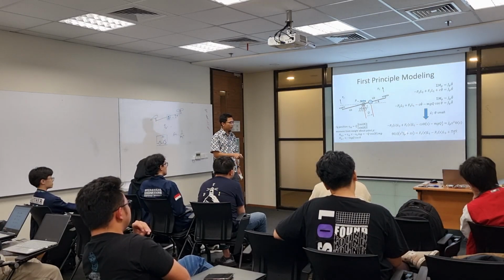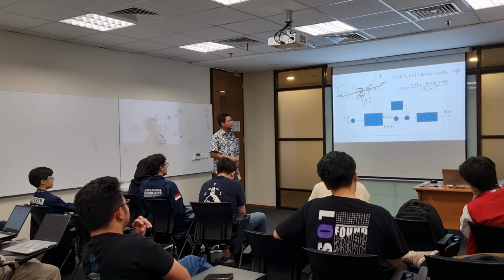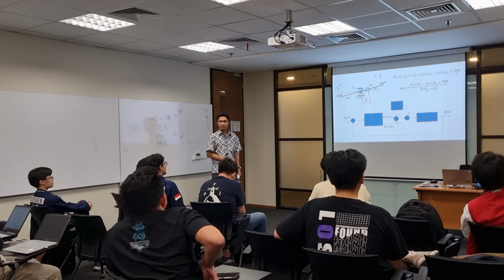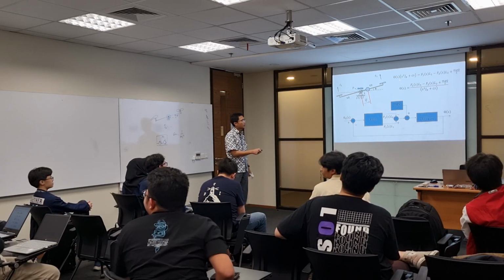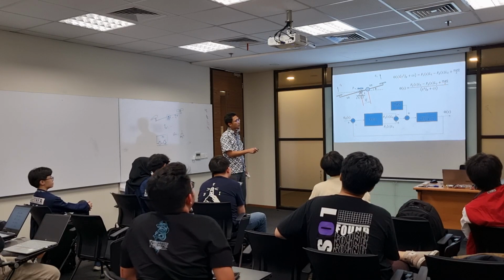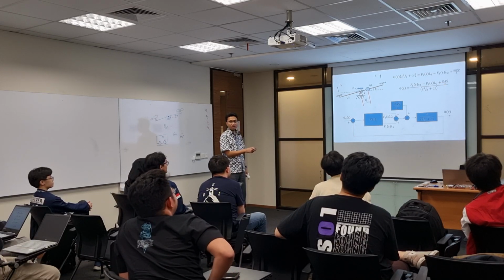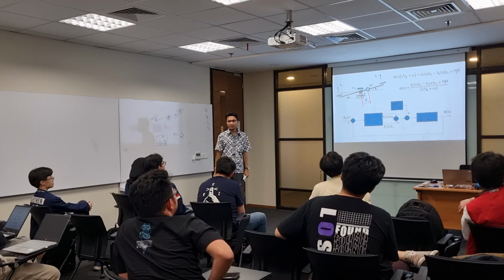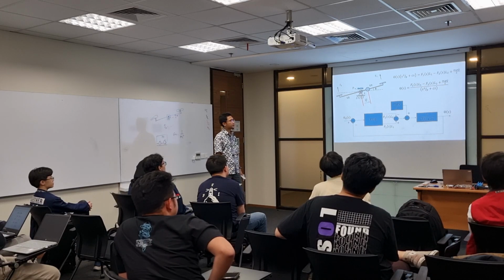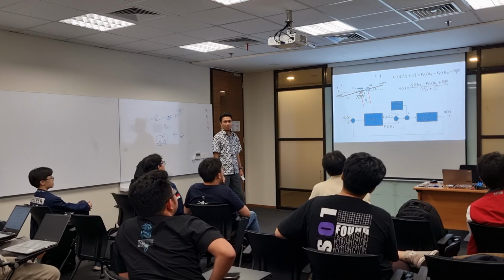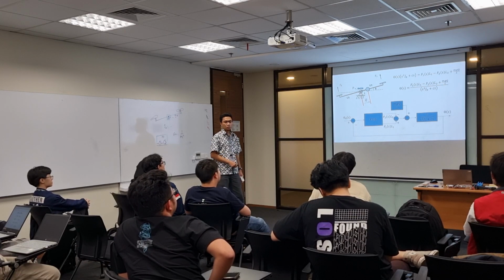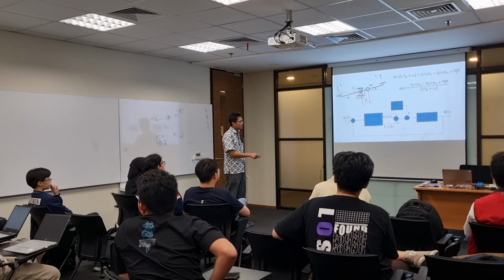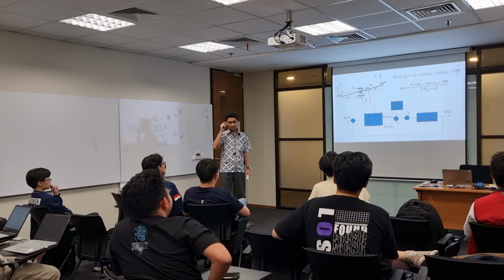Yes, this one over here is the denominator of the transfer function. Because you multiply this term to the output that you want, and this part you move to the right, it becomes the denominator. And this is the block diagram. So far the block diagram looks like this, because the relationship here we still don't know.